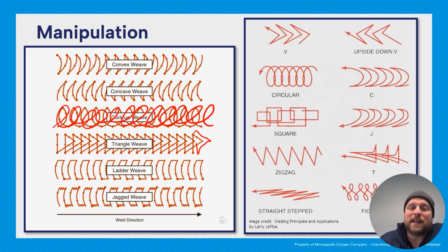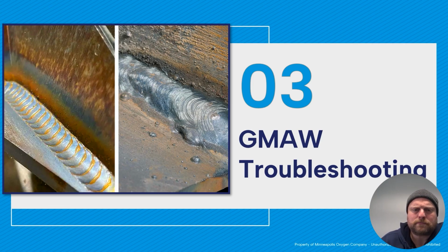So I'll say, in my opinion, vertical up, short circuit is one of the more difficult welds you could ever do. That's why you keep it very thin, and you can do vertical down. But if it's above 1/8 of an inch and you do a vertical down, man, you're going to really have issues with lack of fusion. So it's just something to keep in mind.